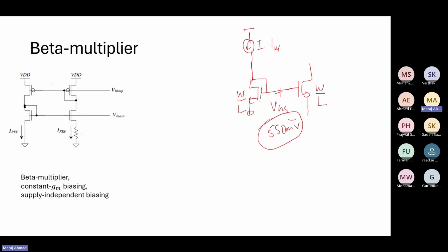So what we do is we don't use this current source. We can generate the bias on chip. So for all NMOS, this is V bias N, this is V bias P. Anywhere in the chip, if you require a PMOS source, take this as the gate. And anywhere in NMOS, if you want a current source, just take this. Multiple places. And in all our design, we have assumed that we have designed this for 1 micro.